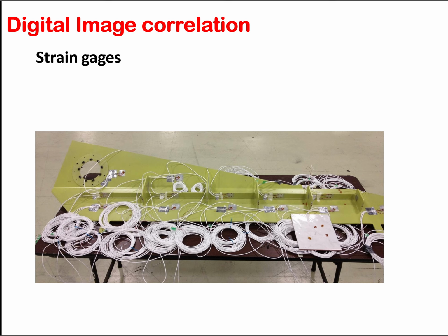But this way, we are going to not see a lot of deformation and deflection information. Right? For example, if you apply compressive load here, you might see a buckling happening at this specific location, but these 2 strain gauges are not going to see that buckling here. And if you perform an interpolation between these 2 strain values, you are not going to see the correct information for the buckling that happens here.